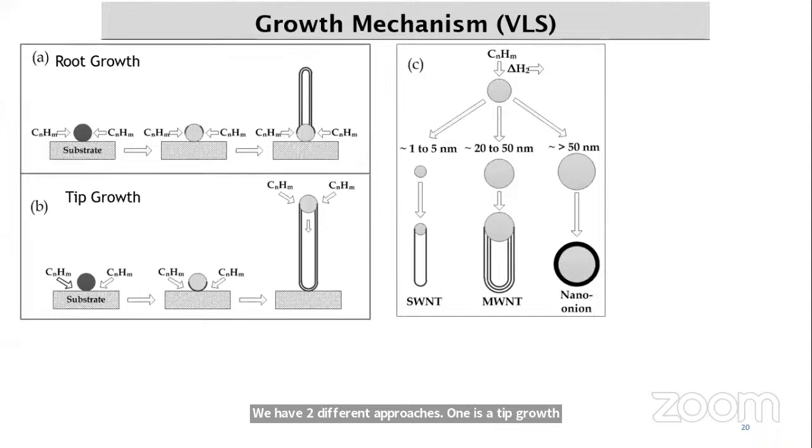Now, what happens in the furnace? The hydrocarbon vapor comes into very high temperature contact with the metal nanoparticle, and decomposes into carbon and hydrogen species. The hydrogen flies away and the carbon gets dissolved into the metal. Then after reaching the carbon solubility limit in the metal at that temperature, the dissolved carbon precipitates out and crystallizes in the form of a cylindrical network, which has no dangling bonds and hence is energetically stable.